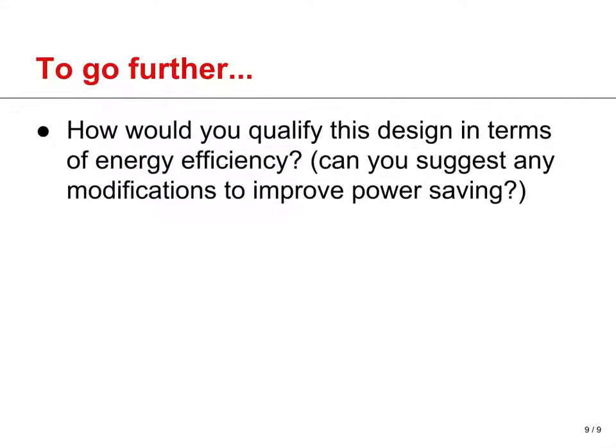Finally, I have a few questions to ask you. One of them is, how would you qualify this design in terms of energy efficiency? And in order to think about this aspect, I recommend you to look at the modulus M counter in the data path. Can you suggest any modifications in the operation of this modulus counter that could improve power saving?